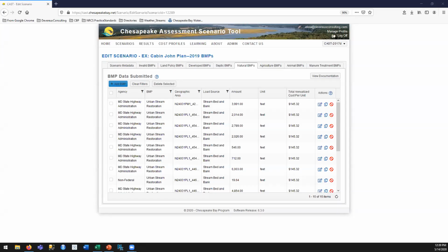But basically the recommendation is that you should take samples every 200 to 500 feet along the project reach, with a sample taken from each soil horizon present within the reach to give you a representative sample. There's also guidance on how to collect the samples and get them assessed in the lab based on some NRCS recommendations. So I'll keep it brief.